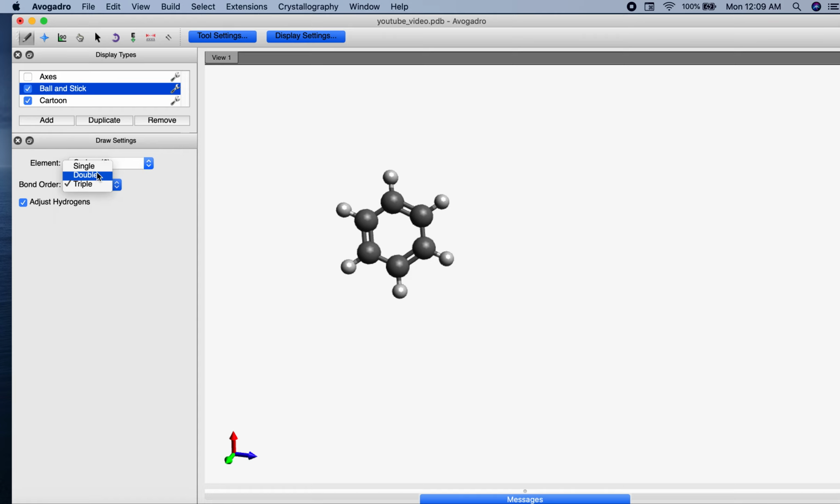Suppose single bond, this, if the adjust hydrogen box is checked, that means when you click the atoms, it will automatically adjust your atoms with hydrogen. So I already showed the atomic model part and optimization, geometry, how to optimize those things. Okay, optimization is done. Now I need the other thing, it's the navigation. This one, it's a navigation setting.